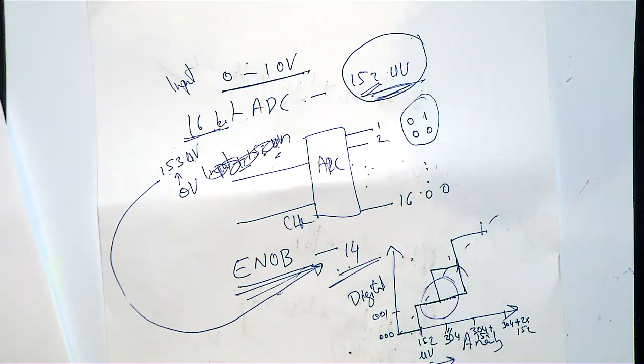I think that's all the important concepts about the errors. These are the errors that happen in the ADC. That's the reason you have the problem with the effective number of bits. Designing an ADC is very difficult, especially high resolution ADCs. The whole point in this lecture is so that you know what is happening when people talk about a missing code. You know what code is missing. It means your analog input is changing by 1 LSB, but the output is not changing because of the DNL.